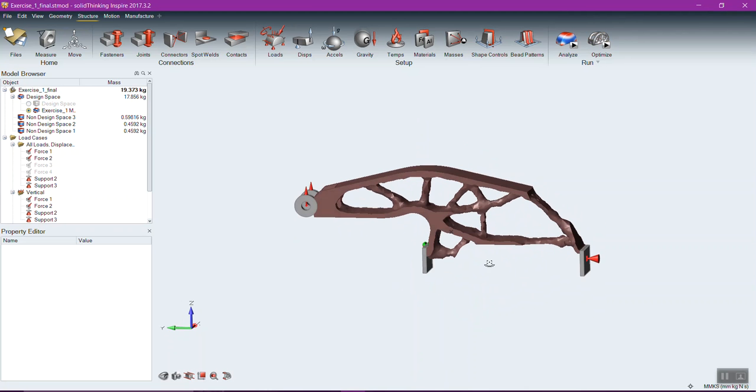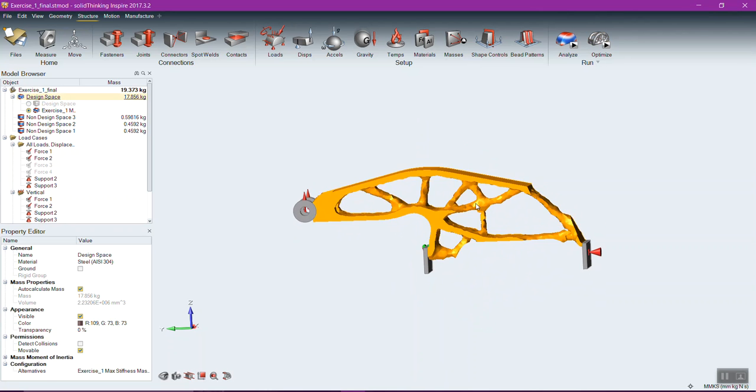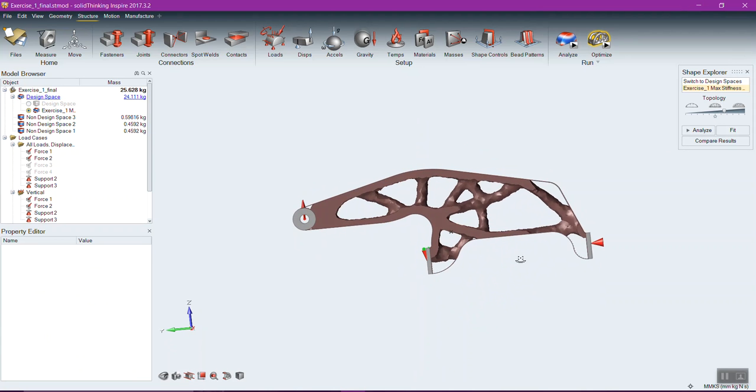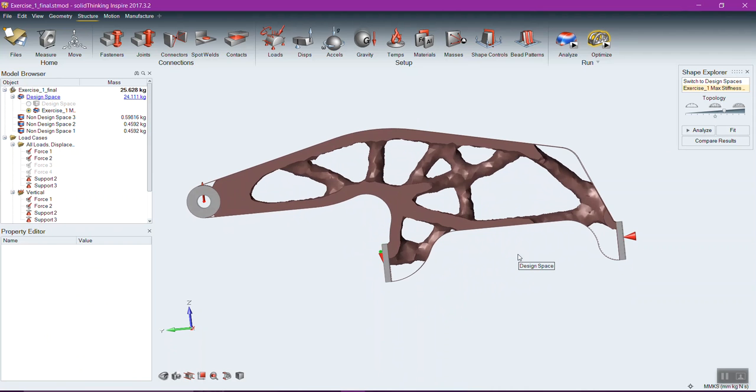This is what topological optimization has come up with. And if I double-click on this, you see some of these little members here are a little weak, so I'm going to use this slider bar to shift it over. And now this is a well-designed part. The thing about topological optimization is it gives you the ability to create designs, to understand designs, to create parts that you never, ever would have come up with on your own. No engineer would have ever come up with that, because we can't look inside the part and see how the load is progressing through there. Topological optimization generates these very organic-looking, very outside-the-box looking designs.